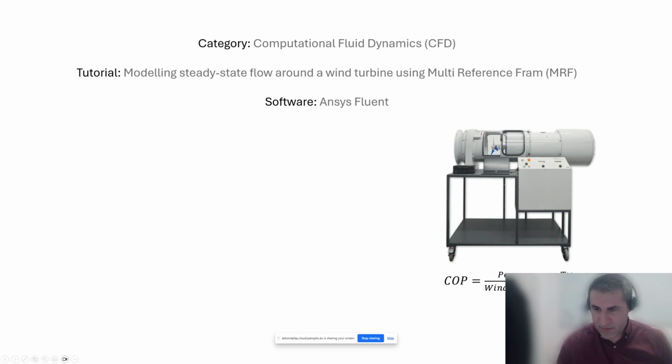Rho is density of air, A is the surface area of the rotor, and V is the speed of the wind coming through the tunnel. So that is kind of the efficiency of the wind turbine. I mean, how much of the wind power is going to be converted to the mechanical power by the wind turbine.